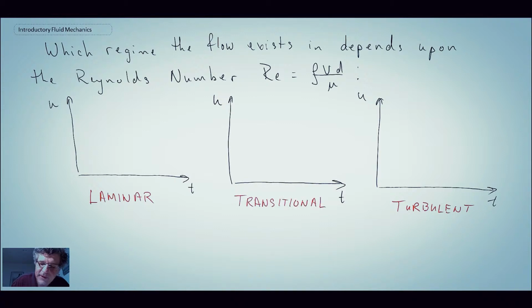And in this region, the equations get a little more difficult to come across because sometimes you're laminar, sometimes you're turbulent, you get these turbulent bursts coming out. But if you were to put a sensor, a hot wire anemometer, into a fluid flow and measure the velocity, what you would find for laminar flow is you'd have something like this. Now, it wouldn't be perfectly flat. There'd be some fluctuations there, and that would be associated with the background turbulence that would be in the flow